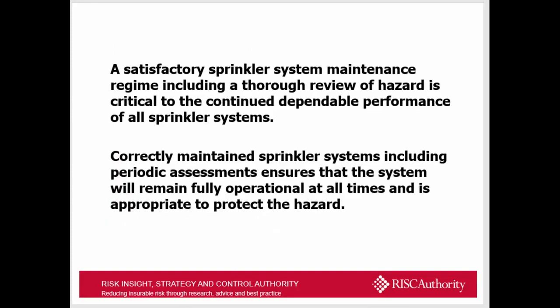It's therefore a requirement that a satisfactory sprinkler system maintenance regime, which also includes the review of hazard, is critical to the continued dependable performance of systems, and that it's correctly maintained, including all the periodic assessments that are required, and obviously that it remains fully operational at all times. And finally, that it's appropriate to protect the hazard. So it will be no good having an ordinary hazard classification sprinkler system protecting a high hazard warehouse that has storage of high category, high fire load goods.